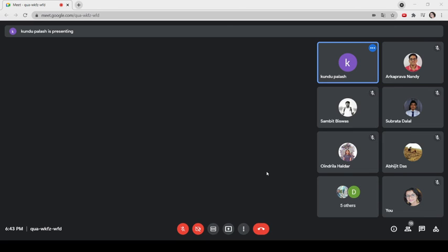So the counter mode of operation is required for real-time applications. Which type of real-time application can you guess? That is event counting. That means there are some events in the form of digital pulses. So how many pulses have been produced by the external sources can be measured in terms of the count. There are suitable applications, that is, industrial applications, automatic industrial applications, which can produce a number of digital pulses, positive going pulses. They can be counted with the help of the counter mode of operation. Otherwise, generally the timer mode of operation is used.